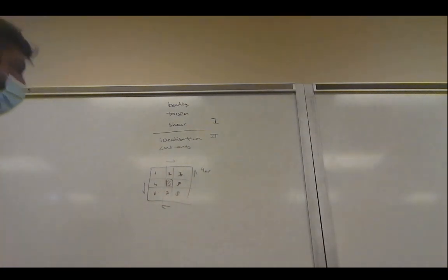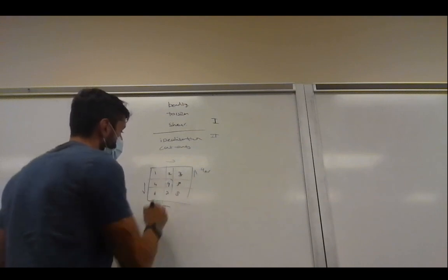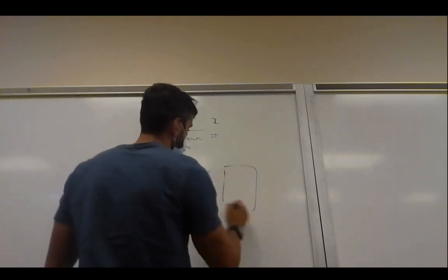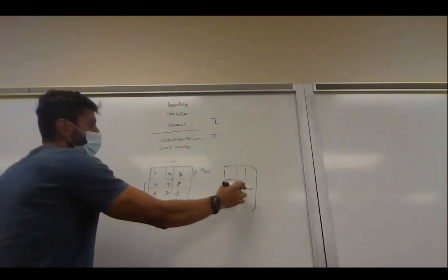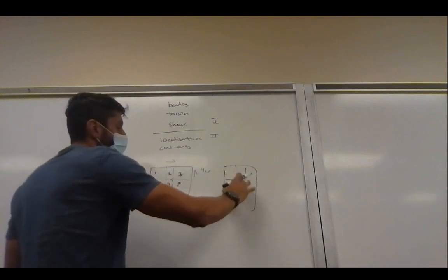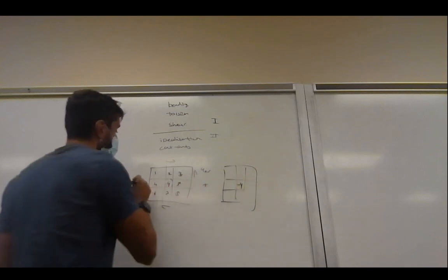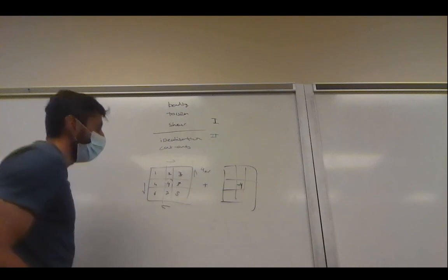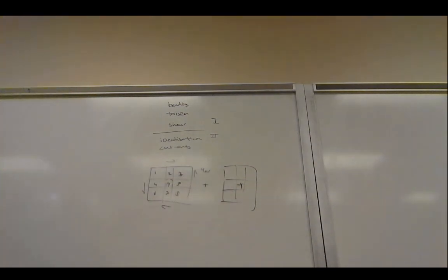And we can do that by calculating the undisturbed field by not assuming it, so this is 9, and then getting another panel and saying, well, the shear flow minus 9 is applied here, so we can find the contribution, the effects of that opposite correction shear flow here, to add these two to get a 0 shear flow in this panel, therefore missing, and then we can add the rest to it as well. And this is towards the end of chapter 22, if I'm correct.